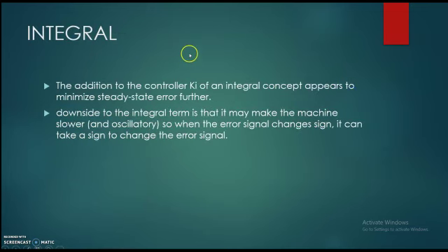Next, for integral, when we add the integral controller, the integral term appears to minimize the steady state error further. The downside of the integral term is that it may make the system slower and oscillatory. So when the error signal changes sign, it can take time to change the error signal.